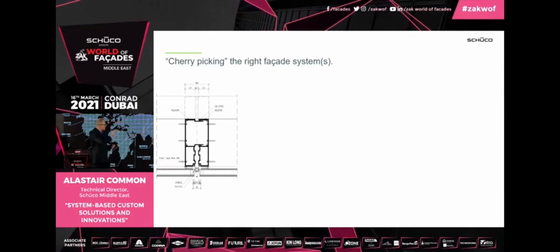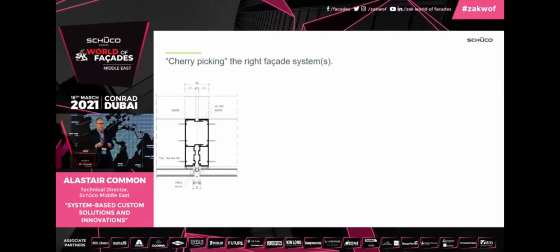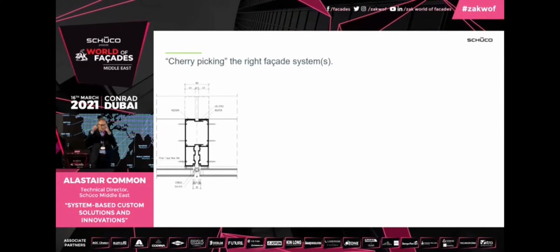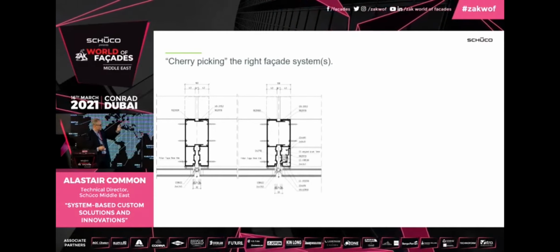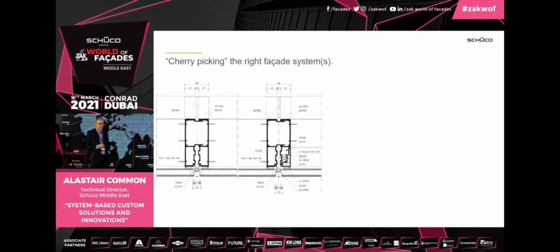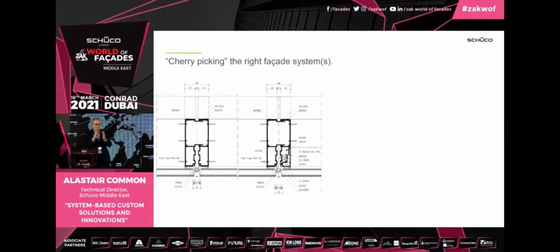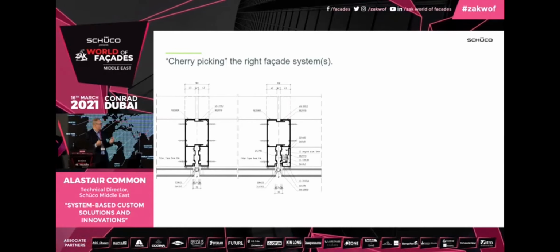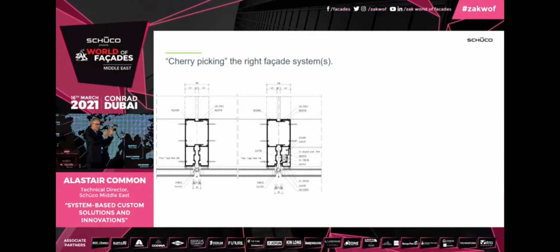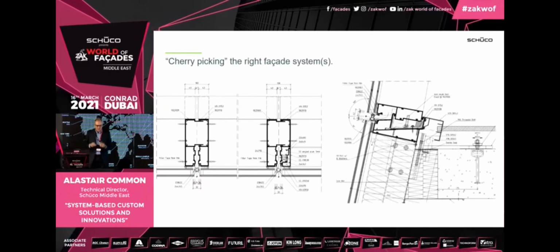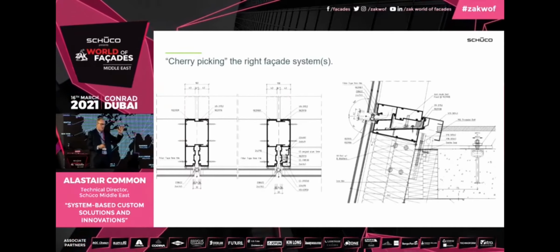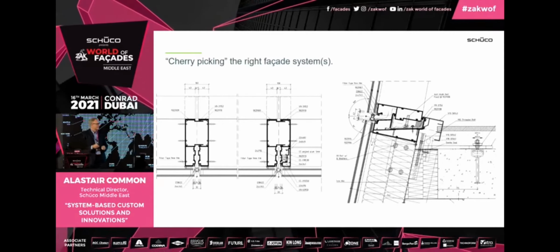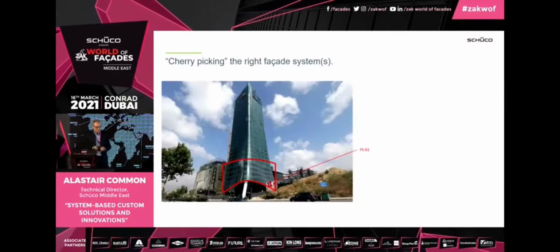One thing, however, you will notice is the grooves within these mullion connections here, because they wanted to have the insert top-hung windows, but they didn't want the classical insert top-hung windows where you see that additional frame. So we had to design this to specifically insert the window within the profiles themselves. So the face width of the mullions is always the same, whether it's fixed or with the top-hung window. But again, we didn't reinvent the wheel here. We took one of our window systems, but we just modified it to be accommodated within the system. The stack joint, fairly typical, but again, certainly the below phases of the unitized, it was inclining in quite a lot, so we had to make sure we designed that stack joint to always be able to drain the water.